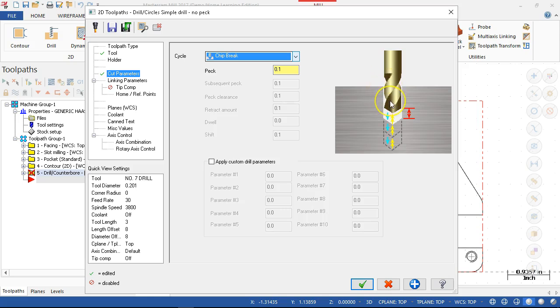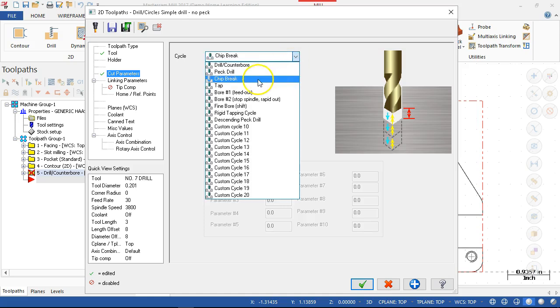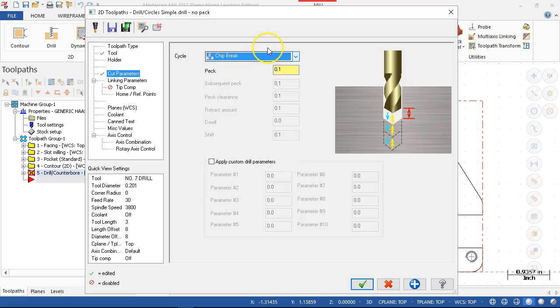Hard materials that want the tool to stay engaged, but we still want to eject the chip, we're going to keep that tool tip warm and cutting. All right, if it's something that we need to flush the chip out, it's the stringy, trying-to-weld-up chip, we need to flush it out, then we're going to do the full retract, let the coolant get in there and go back. Tapping G84, we're not there yet. And then the boring cycles G85 through G89, just depending on what grouping you're running with.